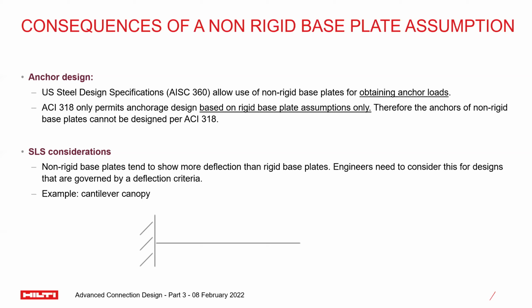So some of you will be thinking, okay, I can't use Eurocode 2, I can't use ACI 318 checks. Why am I listening to a non-rigid base plate topic here, right? And the answer to that is that in the software that we will be showing here today, the finite element method is there to help you make an engineering judgment on whether you can use your non-rigid anchor forces to do Eurocode 2 or ACI 318 checks or not, looking at certain criteria, which I will be talking about. But first, understand that this is one of the consequences, right? And this is something that we really need to watch out for, even before starting our design.